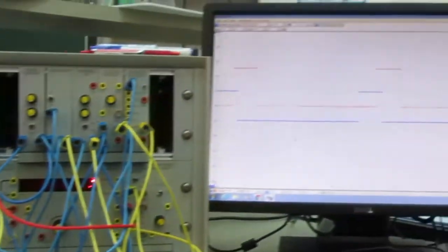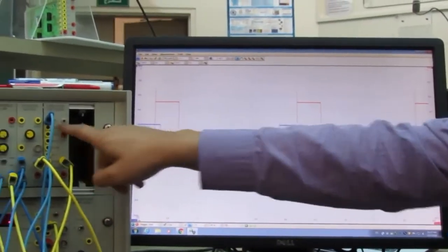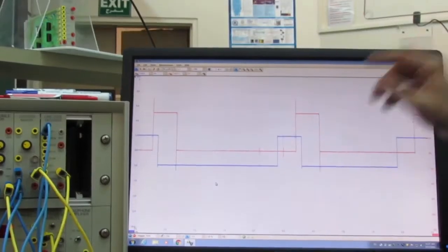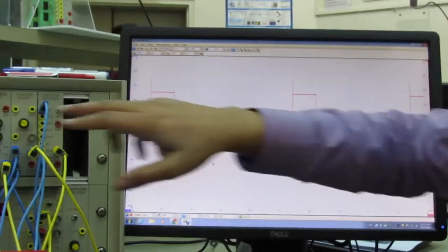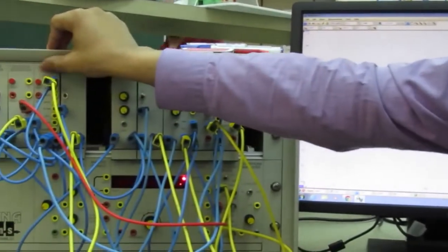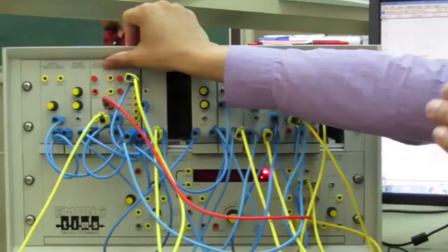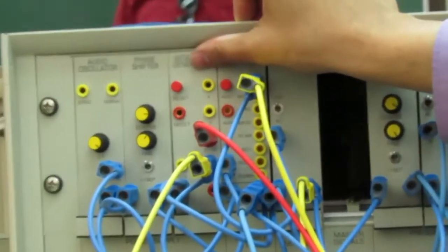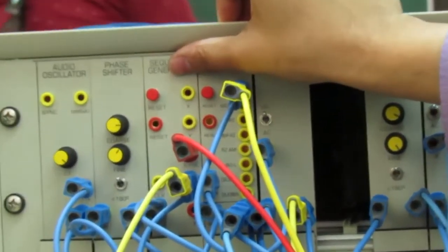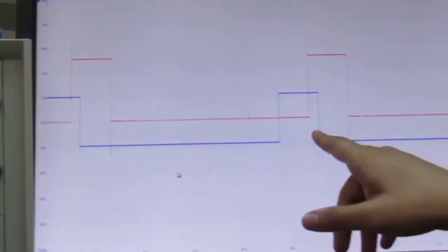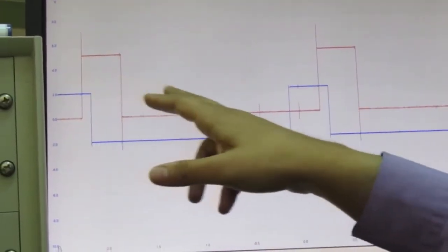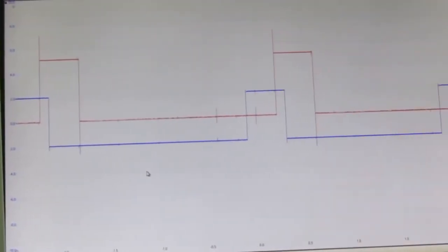If you see here, because I'm using NRZ-L, it was the other way around. When I use NRZ over here, that means a 1 was made to +1 or +2, and a 0 was made to -2, so it was bipolar. The line decoder only changes it back to its original form, right? So there are like 1 0 0 0 0 0 1 0, something like that transmitted.